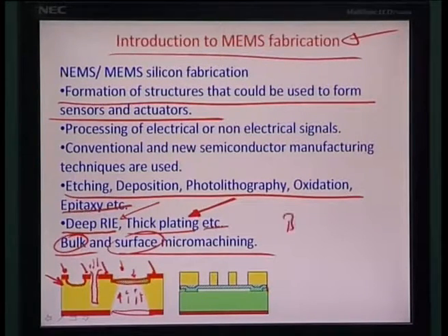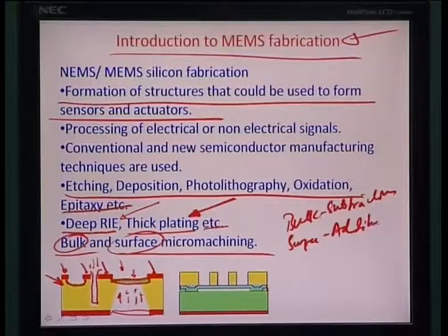So bulk essentially is subtractive and surface is additive. So as you are seeing here in this particular process, you can see you are growing pillars, posts. This is a very fine illustration here. So this was a sacrificial material, as I am showing on the red shaded region, and after depositing a layer of polysilicon on the top of it, you have removed this layer out because it is sacrificial. You can dip it in acetone or something, so you can formulate an embedded channel in the polysilicon layer and between this glass. But whatever it is, you are building it on the surface of a wafer. The wafer really is not subtractively etched out, it is additively built upon.